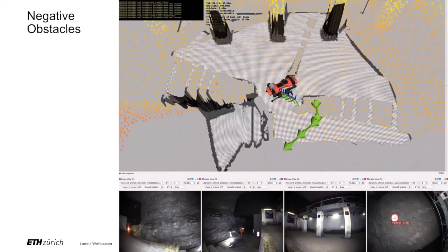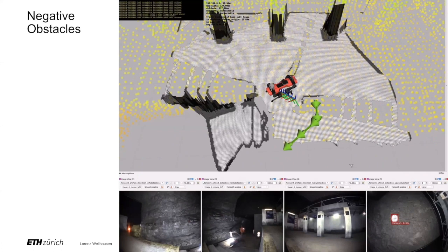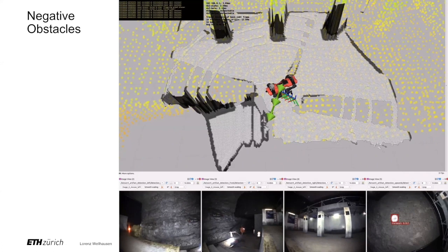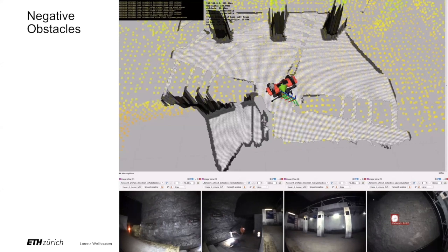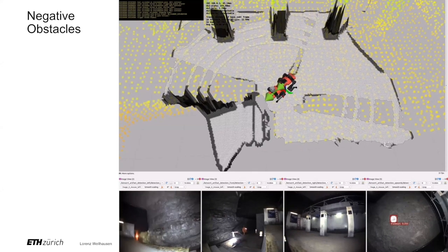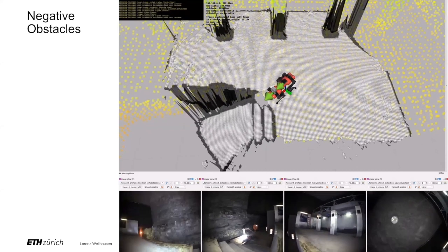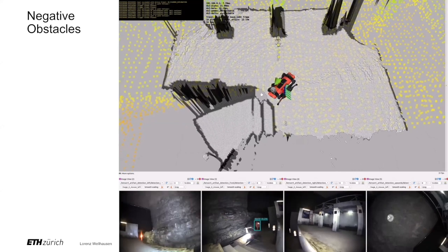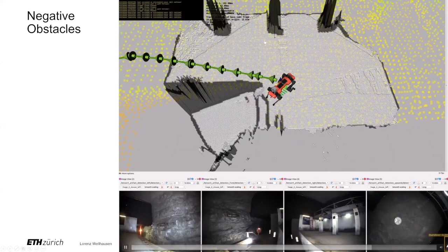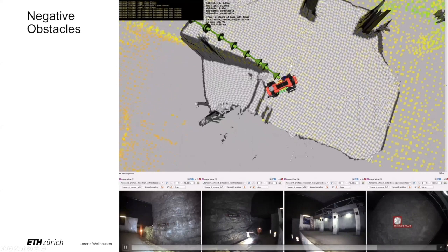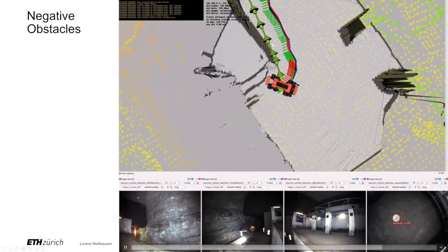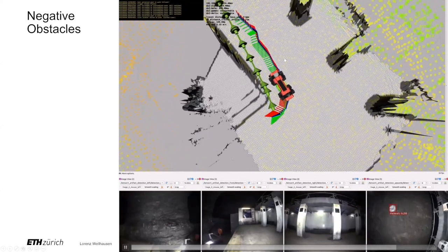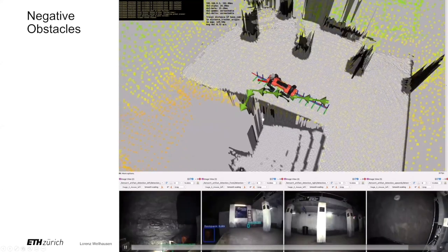Again, if the global plan does not work, it's not possible, the local planner feeds that back and triggers replanning until we eventually find a new path that is actually followable by the robot. So just wait a few seconds because soon we'll go to the left, and there you can see how the cost function guides the path around this edge to have it safe, but at the same time also fast, and follow this path nicely and prevent it from falling down a bunch of times.